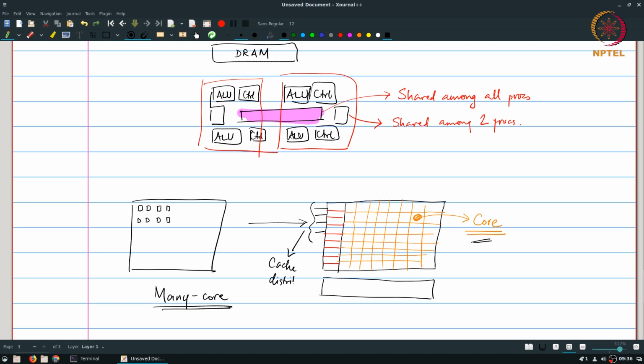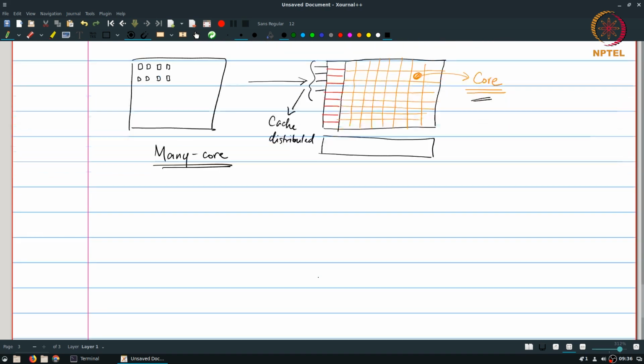which is split up in such a way that either single cores or blocks of a few of these cores together share a certain amount of cache memory and are able to make use of that and share information among themselves. In this way, the architecture changes significantly. The way that you use the silicon has changed dramatically. Whereas previously we had a situation where for a given area of silicon, what you would do is divide it into maybe 4 or 6 processor cores and a certain amount of cache memory.